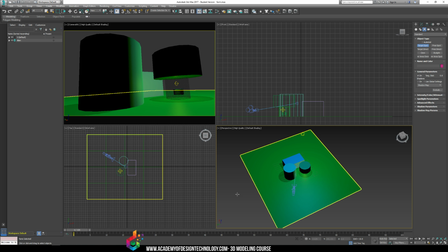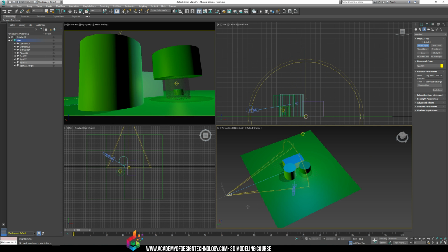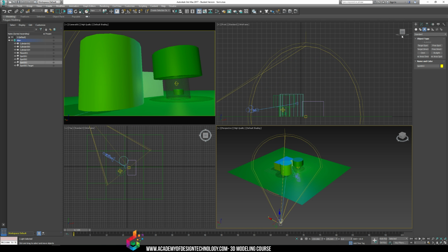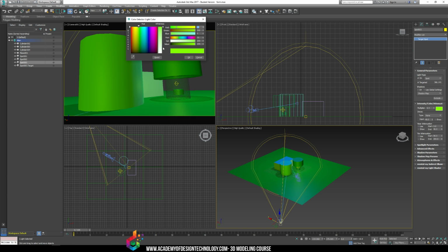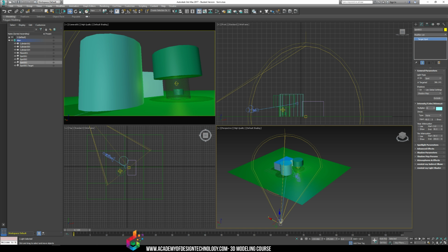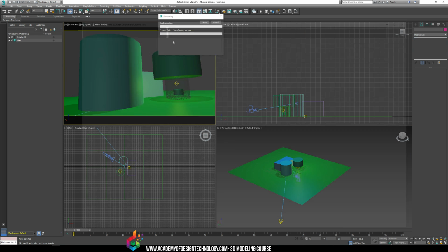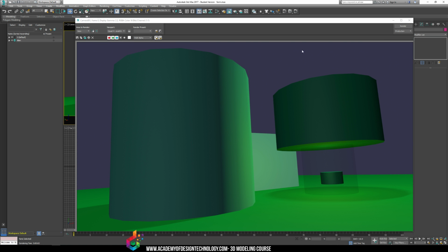So I would actually add a light here, maybe a spotlight here. That's really light, something like this. And I would change this. No shadows. It's a spot, but I'm actually going to change this color to a bluish type color at a really low intensity. See, even 0.1 is a lot, 0.05 maybe. And see, look, we're getting that mood in. Now we can see a little bit of our model. Start changing it around. There's a little bit of a rim here, which I like.